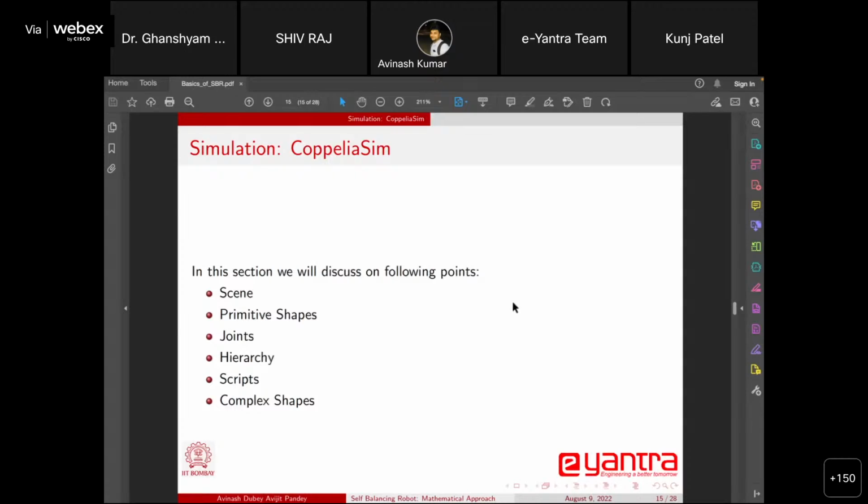So how to define easiness is something of a question. Whether you want implementational easiness or easiness of the tuning. For the tuning, LQR is better, but for applying the control technique itself, PID is better. Okay, sir. Thank you.